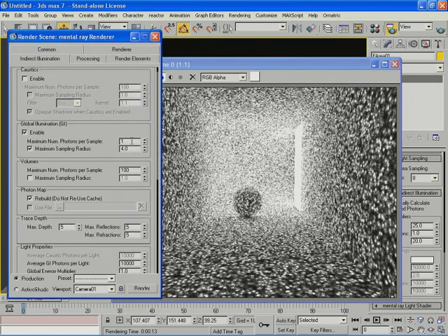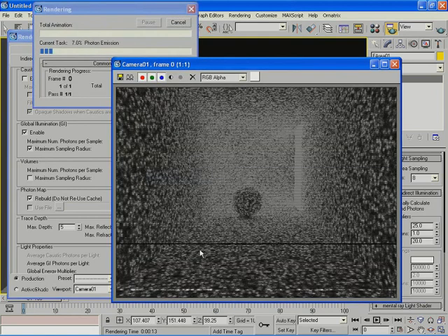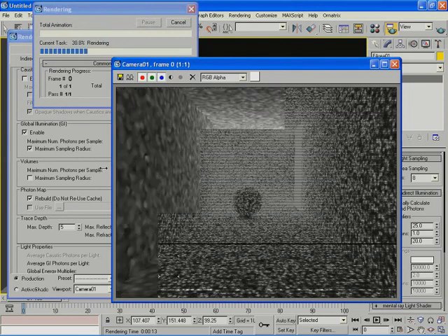I'm going to leave it set to default, because it can blend the photons up to a certain level, and that's it. It cannot override the radius that I have here. So what I really need to work with is the radius value. The bigger the radius value, the more blending between photons. So I'm going to increase that value for now to 15 and hit render.